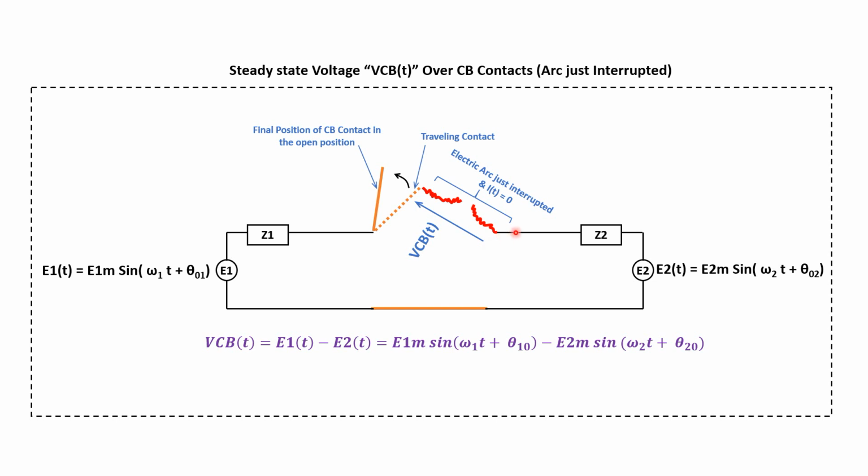Because normally when you're opening that, one side has no voltage and one side has voltage. In this case, the breaking current of the circuit breaker is based on that voltage, and they tell you it's going to be, for example, 50 kA. Just 50 kA is when they have this voltage over that.